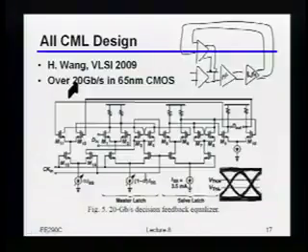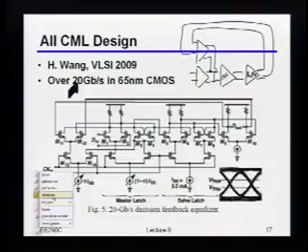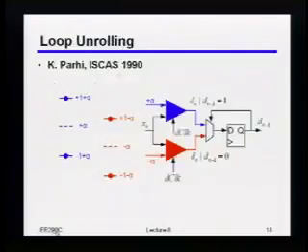Okay? So indeed, you can get up to some pretty high speeds, but even that sometimes is just not good enough. So we'll basically close with this for today, but the last technique you can pull, which again is really mostly focusing on that very first tap, where it's just hard to get that kind of speed, is what's called loop unrolling. Okay? So this idea is very, very similar to what you do in carry look-ahead adders. So the idea here is the following.